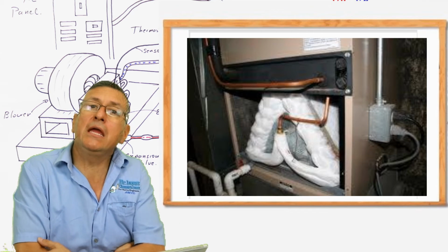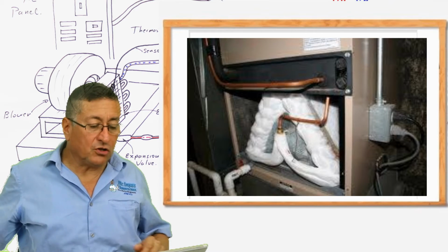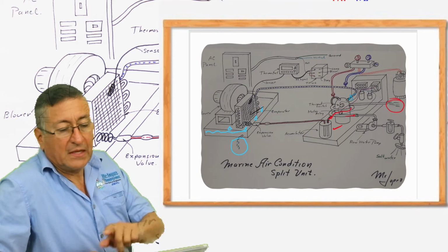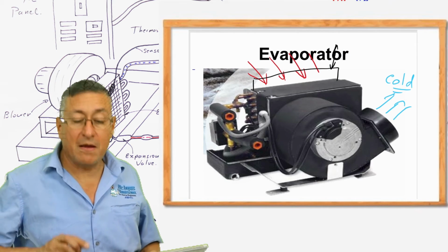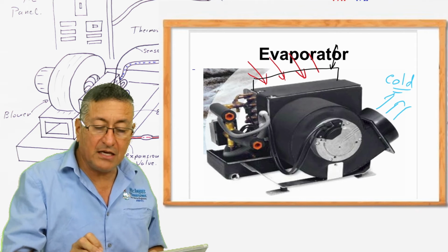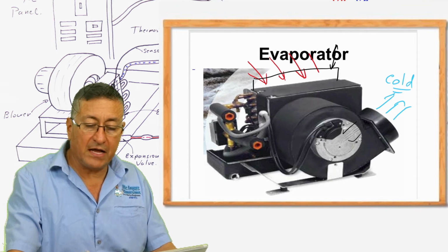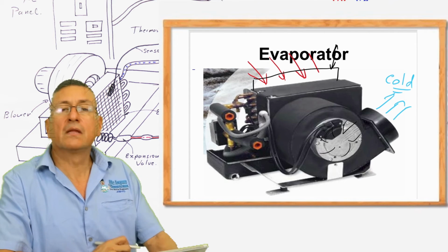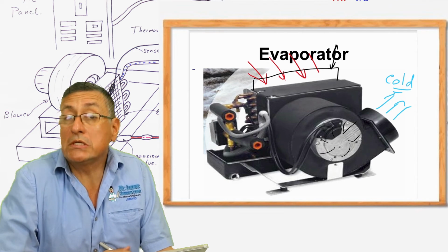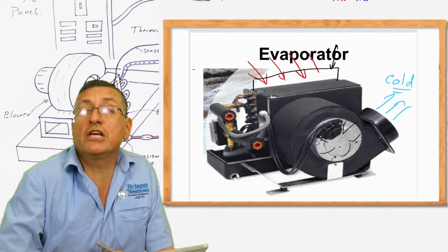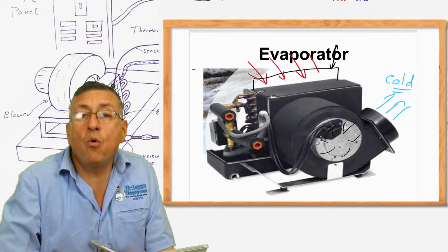For number 3, because here in this picture, the fan located internally, the motor, because here we have a fan, is spinning too slow or is damaged. It's not spinning. The motor is not running. The fan is not working.